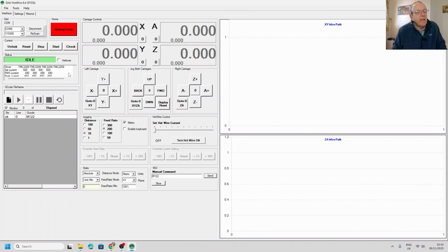Now what I was finding was happening when I was going in and running this setting, it was showing 0. And when it's a 0 setting, it applies full current. So the stepper motors were getting quite hot. So this command allows you to check them. And if you do find they're at 0, what I advise you to do as soon as you've powered the board on is connect the software straight away, because the command comes from the software.